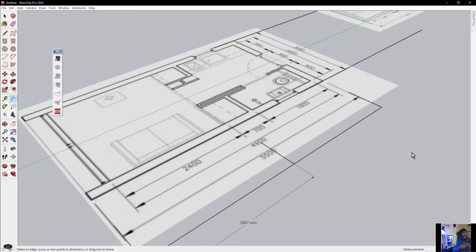When you do have a measurement, the measurement supersedes eyeballing, meaning that the measurement of the house should be 5,500 in length, regardless of however you scale the model, because you have this dimension. Now, let's say that you have this internal dimension. You don't have this. So yeah, then you can trace it because you don't have it. But where you have dimensions, you have to input those exact dimensions and not eyeball it.